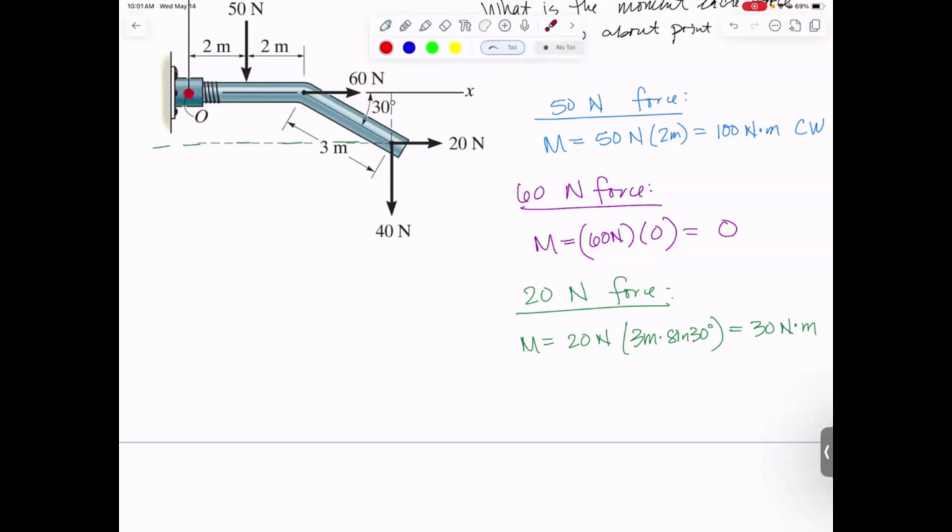So again, think of having a clock. The center is right there. There's my clock. This force is down at the bottom of the clock, pushing to the right. And if it helps you to extend those arrows forever, don't think of the forces just being all the way out here. It's along that entire line. It acts down here. It's going to tend to cause it to rotate that way, which is counterclockwise.